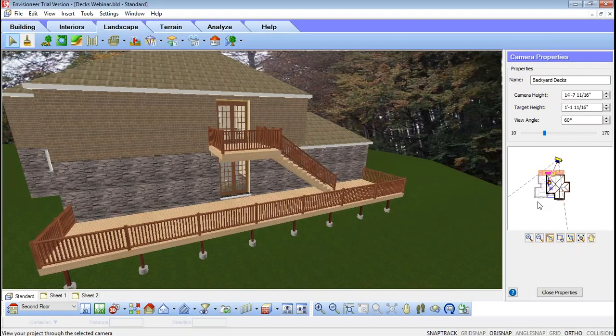Does the pad tool put the concrete pad level with the house floor level, or does it set it lower by 6 inches, plus or minus? Like I was saying, the pad itself attaches itself to the terrain. So depending on what your building locations would be and how far off the terrain your ground floor level is, that's what's going to define the difference between your ground floor and your pad location.